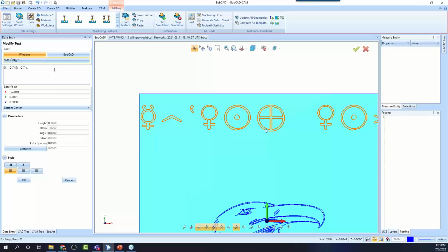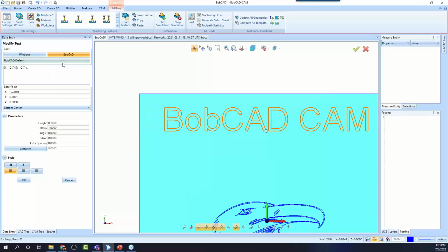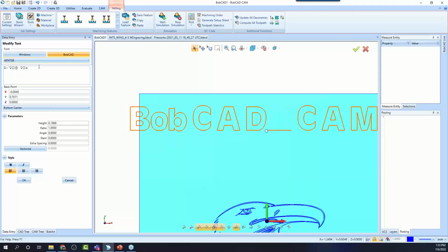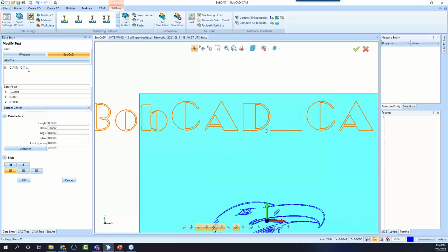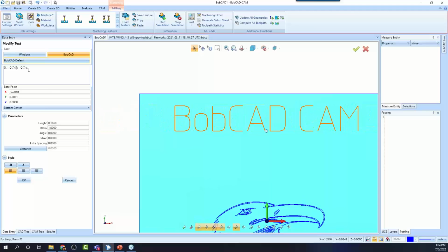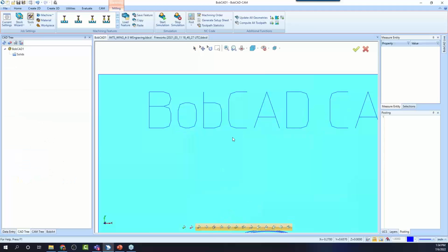Another very useful tool. But what I want to do is switch this over to one of the AFNs, and I'm looking for a Centerline one. Okay, Centerline Fonts, here we go. This is what I'm looking for, and we'll say okay. All right, so the Centerline fonts, instead of going around the outside and the inside, go just down the center. They're very basic stick type fonts, but what it does show is this intersection that I was talking about, where you have lines that are open profiles but then intersect with each other.